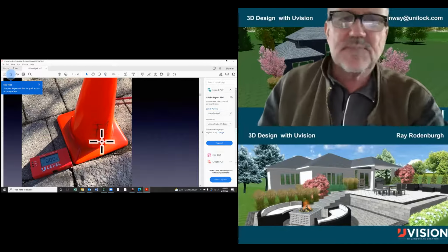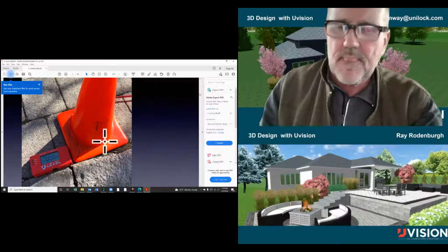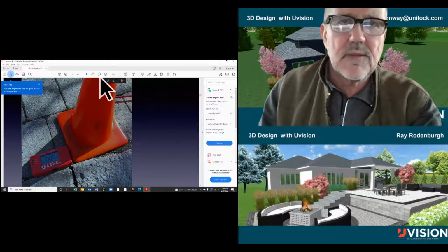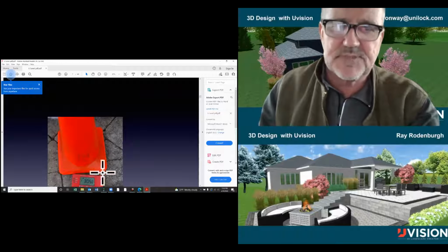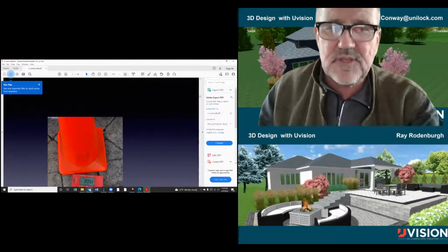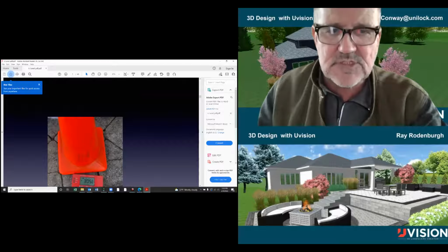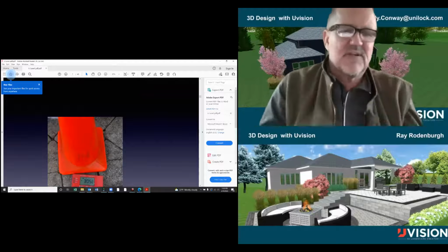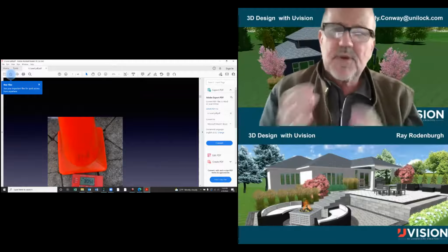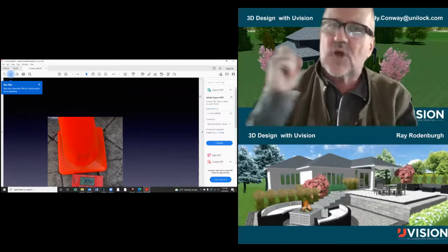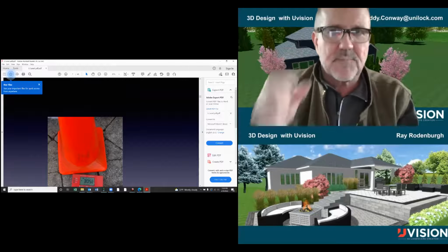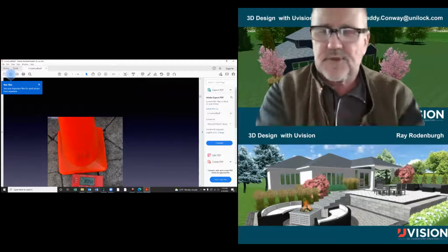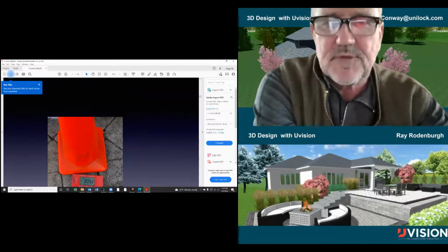So there's my position 1. So I literally go around the site. Here's position 4, and that reads 3 feet 5 inches, 15/16, so nearly 3 feet 6 inches over my first reading, which is 0. My first reading is my grid. That is now my grid. So this is 3 feet above it.